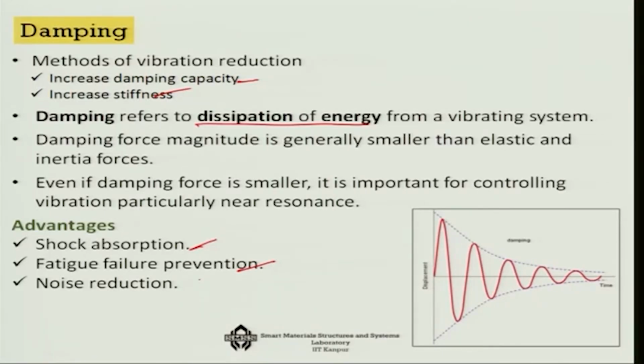etc. So, this is typically an under damped curve, as you can see, and this is under viscous damping, and you can see that the response is coming down exponentially. As the damping increases, this will be more and more, and there is something we call the settling time. That means, in comparison to the initial value, when the initial amplitude comes down to within say 2 to 5% level, we say that the vibration has damped down.